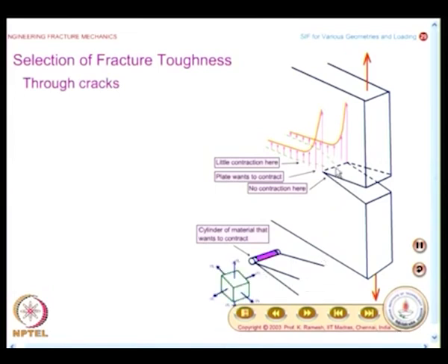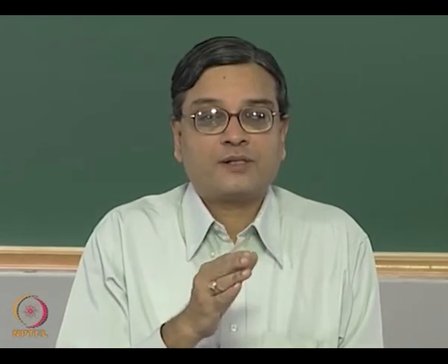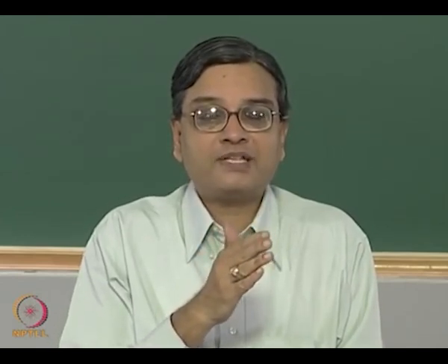What you can always notice is, when you have a stress concentration zone, normally you come across a uniaxial field changing into biaxial field. But in the case of crack problems, for thick plates, you have to also consider one more aspect. We have already seen, when the crack tip is very sharp, sigma x equal to sigma y. If the crack is blunt at the crack tip, you will have sigma x as 0.